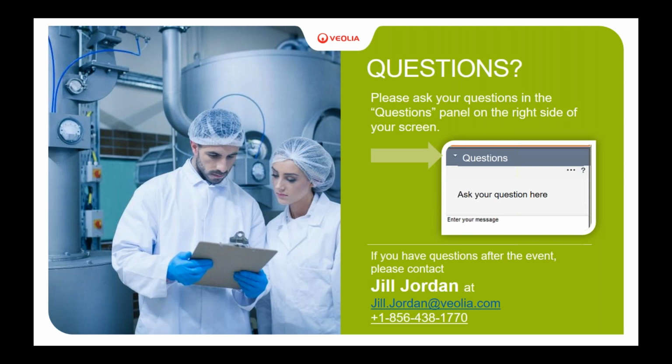I'm going to say there is no max, really. It depends on so many other things. Typically, I don't like to see more than a 25% plus or minus the average over a day. That's one of the reasons we like the idea of the calamity tank, because if you have a big dump that comes down in 5 minutes, you could easily have to treat 100 times your average daily load for 5 minutes, which the bacteria probably aren't going to like.